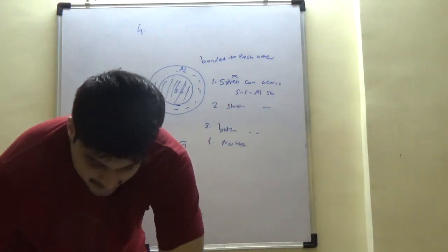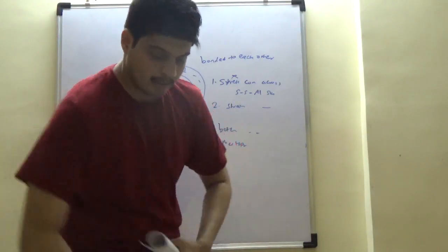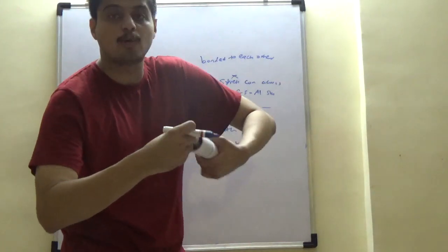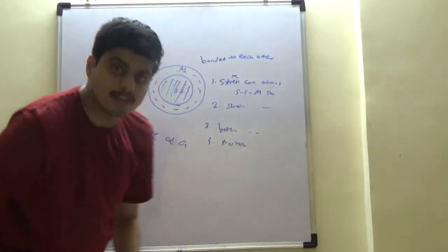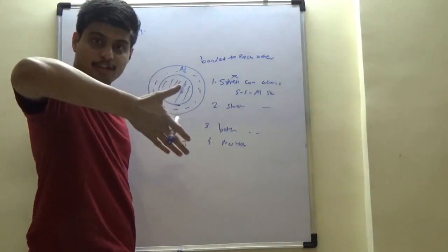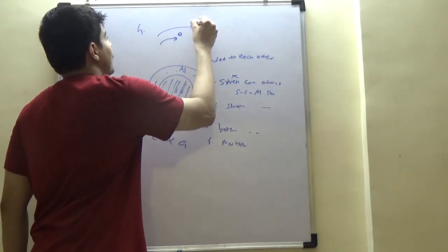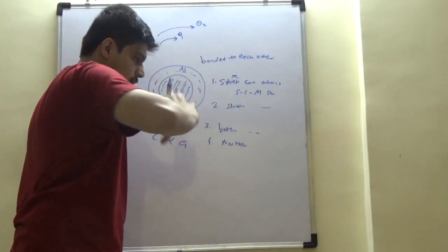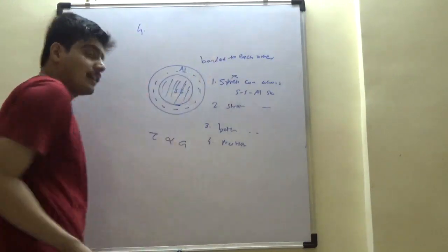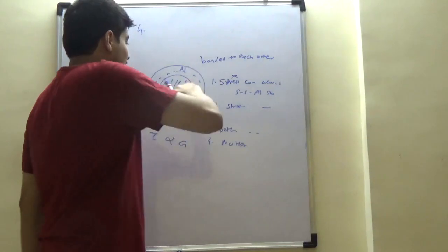Otherwise, we can demonstrate it this way. If there is one bar inside which there is another bar, and these are not bonded but free to rotate with respect to each other, based on their material properties they would have different twists, different theta dash. If SS moves by this angle theta and aluminium by theta 2, you would see a slip. The slip is not allowed, which means, depending on which tries to twist more, the second will resist. This is like a thermal problem.